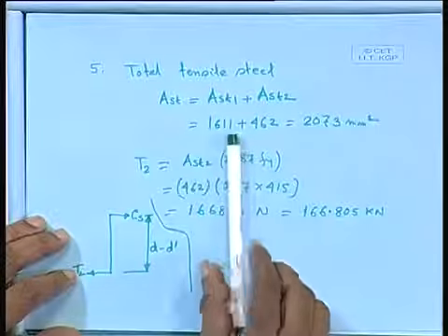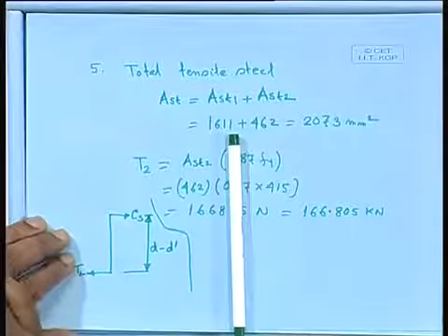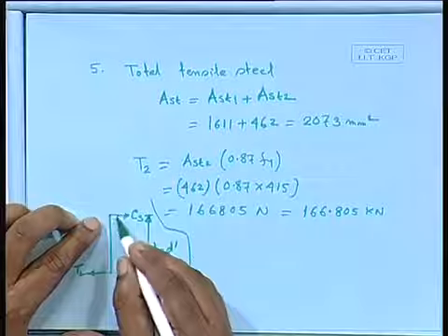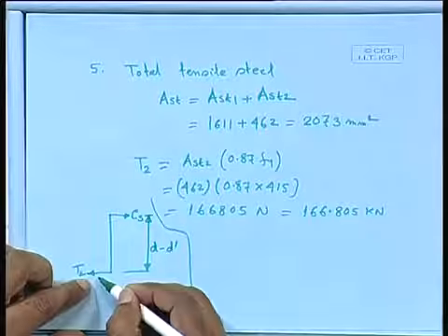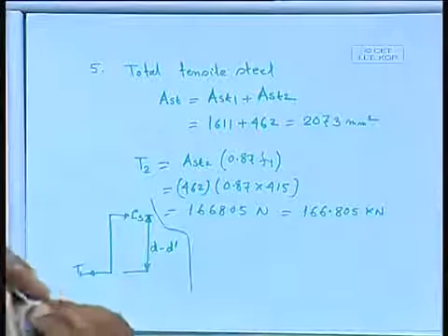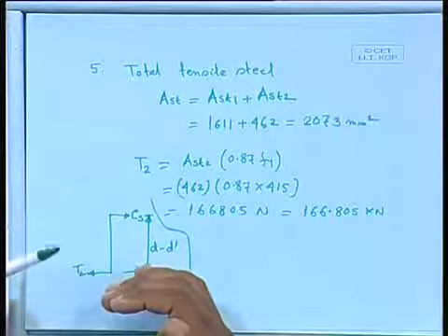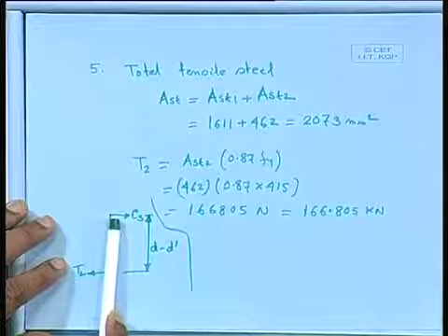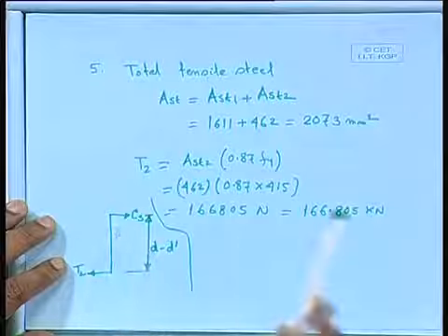We have to provide the reinforcement on the compression side in such a way that it will be in equilibrium. So Cs should be equal to T2, but the strain at this level is different than the strain at the tension level, because here the strain comes from the top fiber concrete failure, that is 0.0035. So on the compression side, the steel will never reach the yield stress 0.87 fy. We shall find the stress by getting the strain at that level and the corresponding stress.